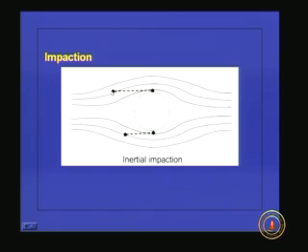So, what will happen? Since it has high mass, high density, it will have inertia. So, it may not follow the streamline of water. It will take another path like this. See, because of the inertia, it may take a straight path. Because of that, this particle can come and hit the filter media.